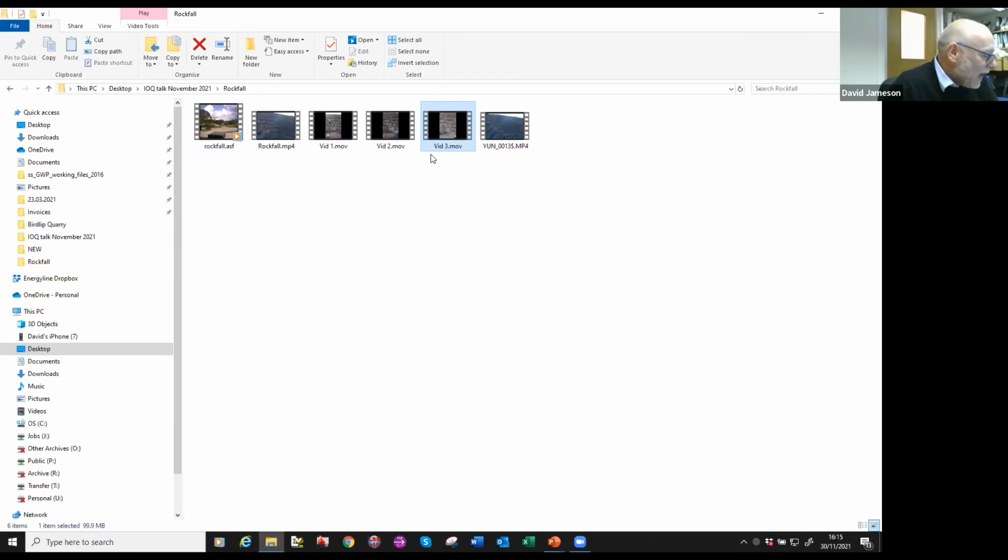You'll probably see that rather than blocks bouncing a long way out from the bottom of the face itself, as you often get in unregulated rockfall analyses that have got any scaling on them, the materials when they fall down the face either slide or don't bounce very high off the face, they bounce only a couple of meters out from the face. So let's have a look at a couple of examples of blocks falling down the face.